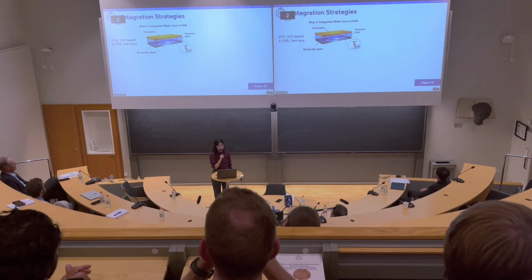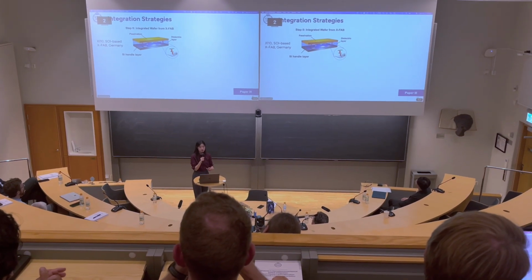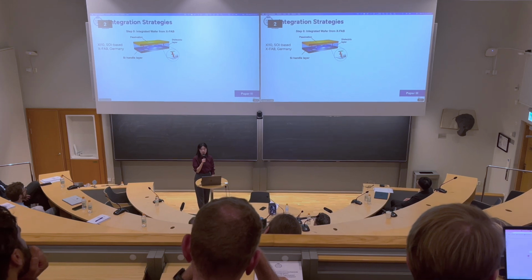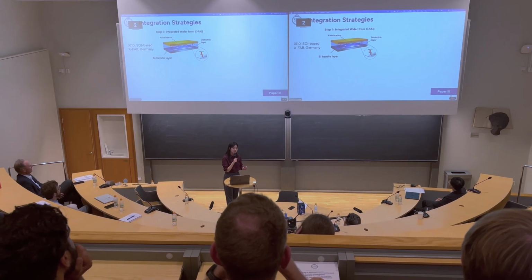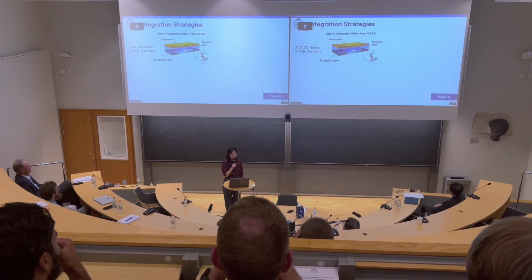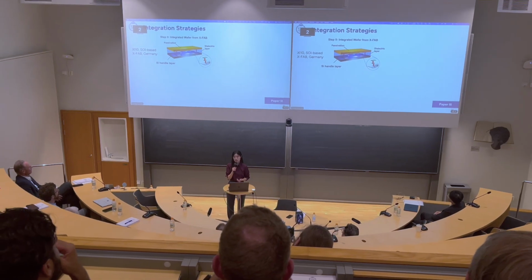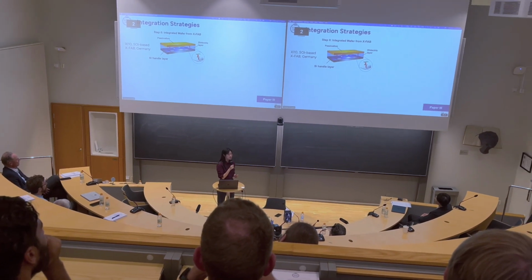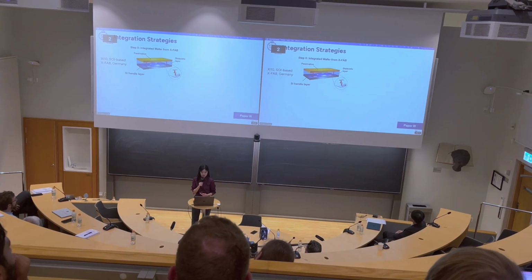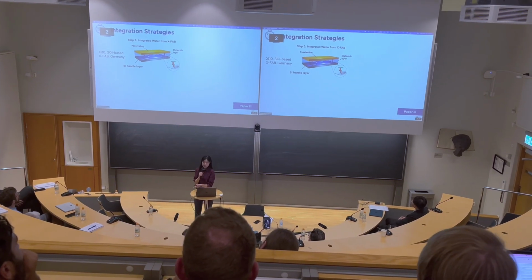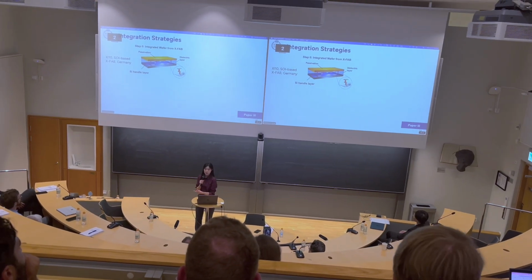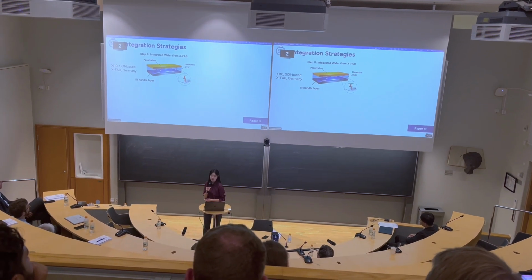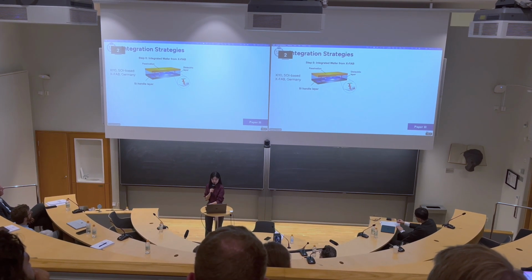So first we have this integrated foundry wafer, which is built by depositing the back-end routings and dielectric layers on top of the SOI wafer. And at this foundry stage, the switch is not yet patterned, and the silicon device layer is buried inside the back-end layers. So in the first post-foundry process, we have to expose the silicon device layer and get access to it.